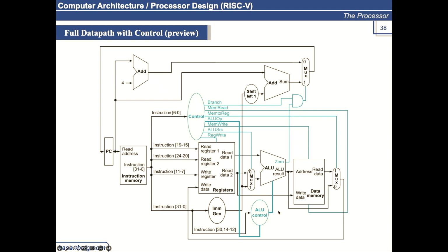So first of all, why are we splitting this? Why can we not just generate a 4-bit signal and wire it into the ALU directly? The first thing is, in order to do that directly, we not only need to analyze the opcode, but also the func3 and func7 fields. When we are analyzing more bits, we need to make more comparisons, like an if-else structure.